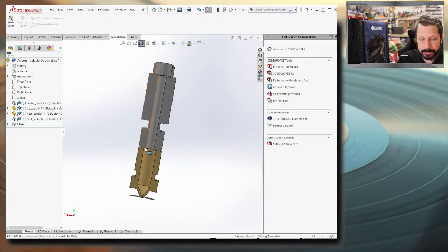And if there's a tiny little gap, the end of your Bowden tube is not square with the top of the nozzle, then softened filament is going to leak out the side of that gap and harden, or at least solidify to the point that it's not easy to extrude anymore, and that's going to cause under extrusion, and because not as much filament is going to be coming out of the nozzle, it's going to hang on that bulge, and it will eventually probably cause a clog.